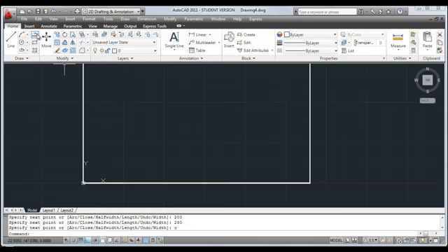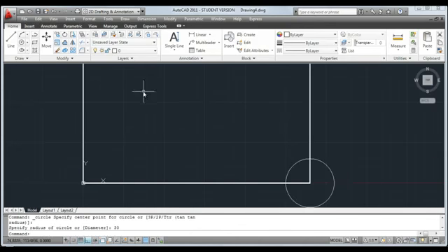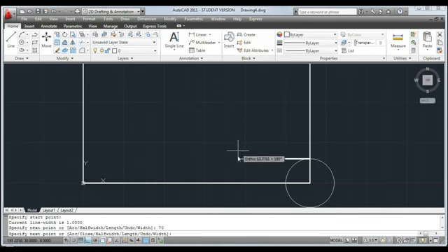And again, I'm still going to use polylines for this. The title block will be 30 millimeters high and 70 millimeters long for this A4. So I'm going to draw a circle from here, the radius of 30. That intersection then is where I'm going to start my polyline. Go from here, 70 across to the left and 30 down. And then return to finish, so raise off that line.